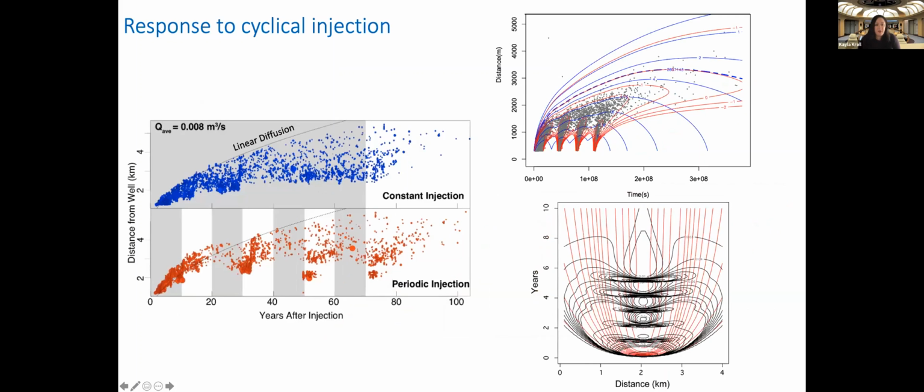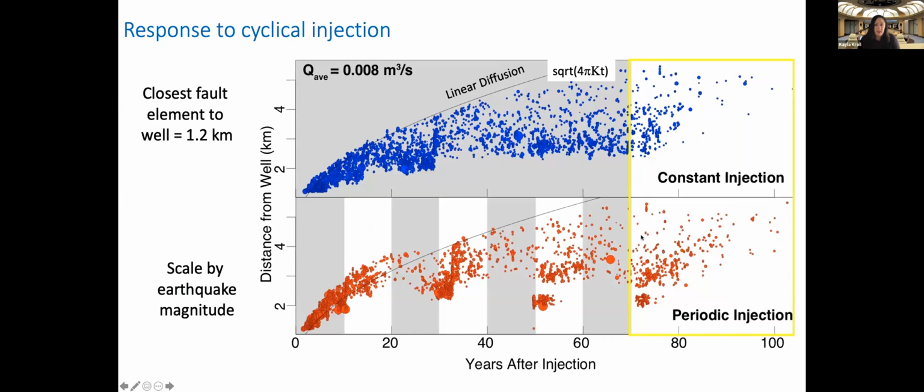This behavior, this clustering or high rates or bursts of seismicity, is very similar to the behavior that Jim showed yesterday for the somewhat simpler rate model. And then finally, we see that there are quite a few events in the post shut-in period here. Some of these events occur when the overpressure on the fault continues to rise after shut-in, but at larger distances from the injection well. But most of these events occur on the fault surface as the overpressure is actually decreasing. This is the point at which the overpressure returns to about or less than 50% of the maximum pressure, and we see a high density of seismicity in both of these cases.